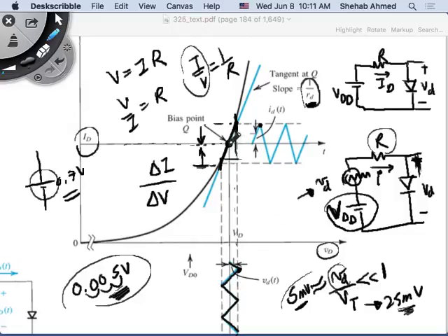I can apply superposition, meaning I can deal with this circuit alone here, and then I can construct another circuit with only this ripple and this resistor and this diode. And I assume that the diode will be forward biased. But what do I put instead of the diode? In this case, what did I put instead of the diode? What's the model that I used? This forward drop model, right? I put a voltage source here, and I subtracted VDD minus 0.7, right? And I calculated the current. That's what we did in the example, correct?